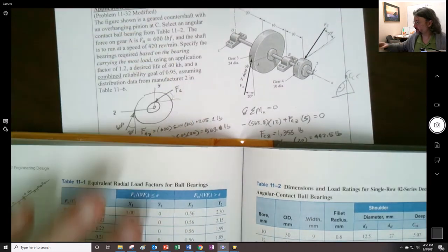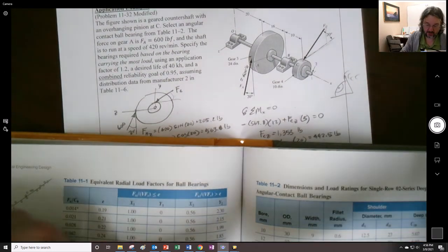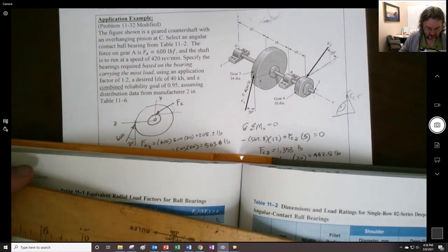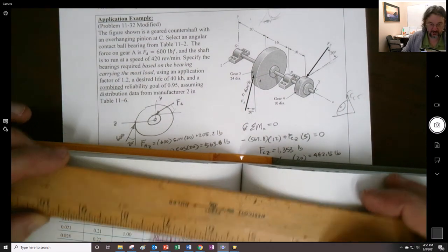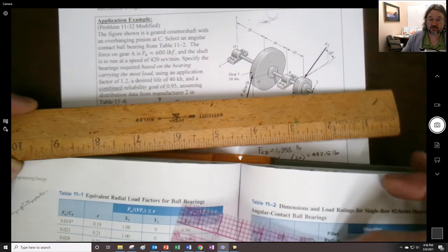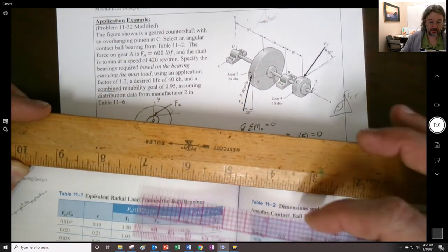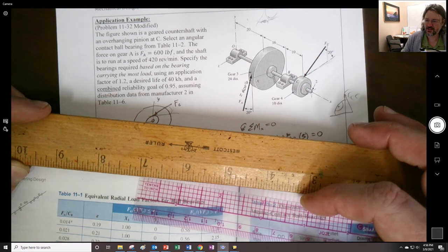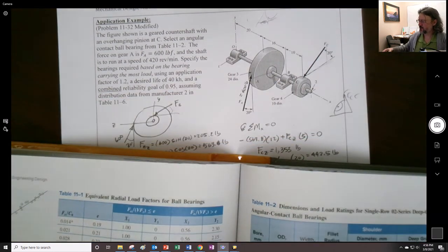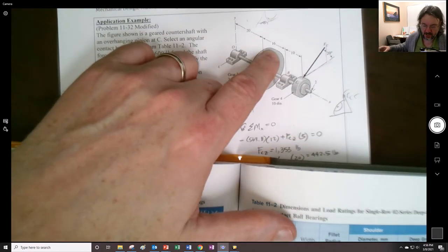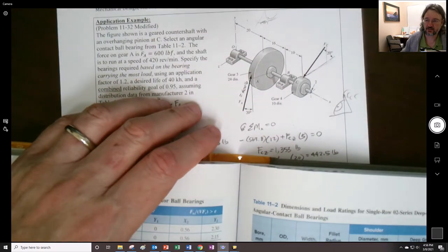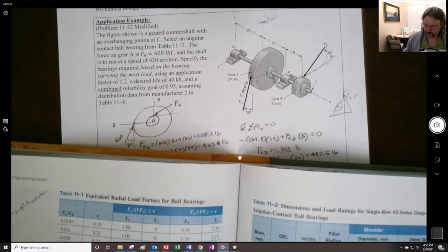Now compare that to the size of this right here. It's 10 inches, right? So this thing's that big, and so that shaft is coming in to be here, right? So here's the 10-inch, and there's that. That's a pretty big bore of a bearing, right? And imagine we had to put the step in there. So I'm wondering if maybe this design of this length isn't too far over cantilevered with that 10 right there, right? These are design choices that we might have to make.